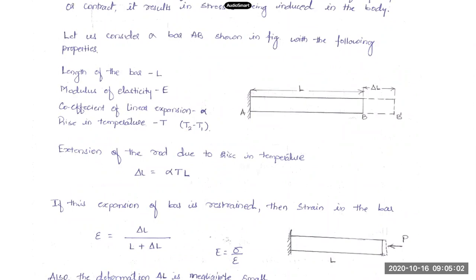If I am interested in only one dimensional change, that is a change in the length, then I'll be dealing with linear expansion, the coefficient of linear expansion. Or else if you are interested in volumetric expansion, then this coefficient will be for the entire volume. But in any case, the coefficient of thermal expansion is required. With this, we can estimate what will be the increase in the length.